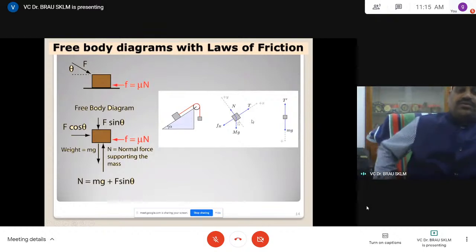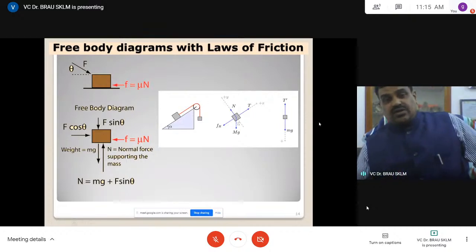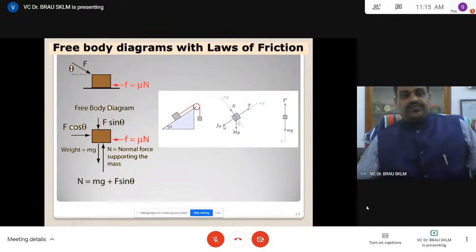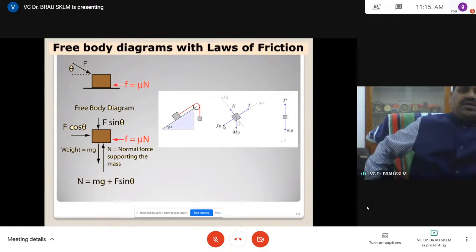See, that is how we will try it. If there is no friction, Fr is 0, there is no horizontal, only T is equal to mg sin alpha. But here in this case, the total vertical equation is N equal to mg cos alpha. Horizontal is F for frictional force, m2g sin alpha, the two components in this direction, tension in the opposite direction. Now the tension can be determined by T equal to Fr plus mg sin alpha. Now substitute the given data and obtain the answers.